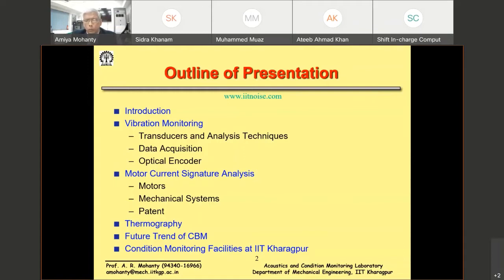And with reference to the afternoon, where we have mostly the recent advances in instrumentation, I'm going to mix some of these techniques now and some later on. So coming back to my formal presentation, I'll be talking about condition monitoring. There are many ways we can do condition monitoring, be it vibration monitoring, or the oil in a gearbox, or the lubricating oil, or the hydraulic oil in hydraulic systems.